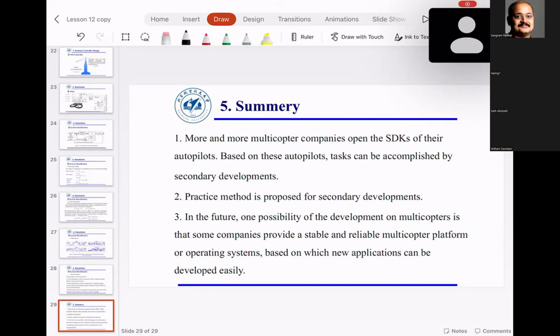So, main models, RGB data: the vision sensor is running slower than the actual control loop. So you have this rate management box. You'll see here is a rate transition that would take this low frequency image data and oversample or interpolate it and send it.